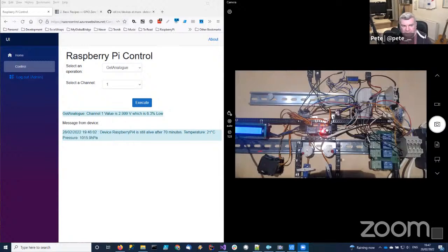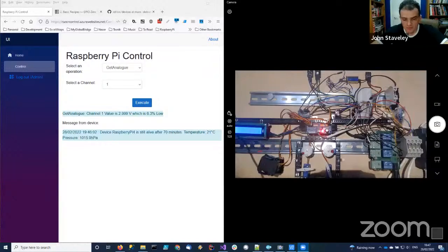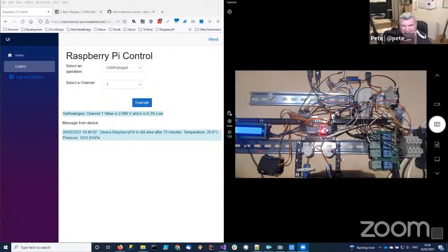The other thing I don't like about Raspberry Pi is you have to give it a controlled shutdown. With an Arduino, you can just yank the power out, no problem. But if you do that with Linux too many times, it won't come back up again. Now, having said that, I have pulled the power out on quite a few occasions, and I've got it back up again. But the first thing it says in the book is press start, shut down. Do not do it any other way. Well, obviously you can do it from the command prompt as well, just as easily, but the same idea applies. John's right. Yanking the power is often bad for the SD card.